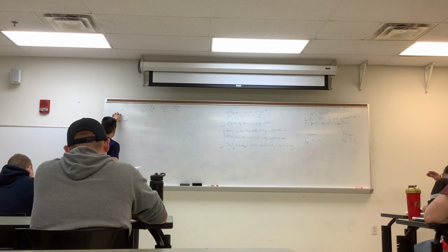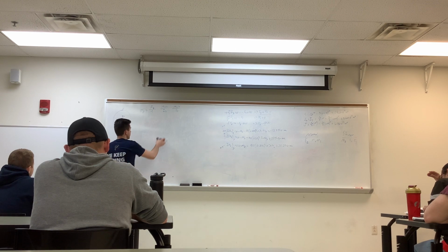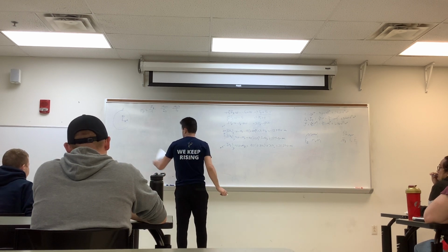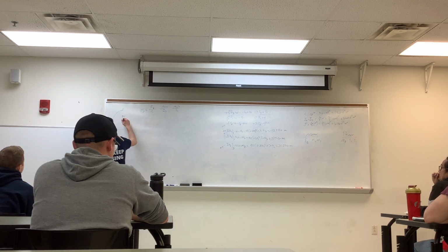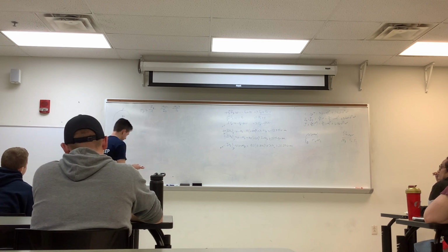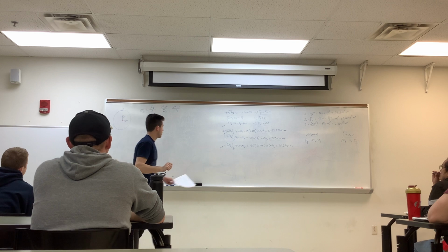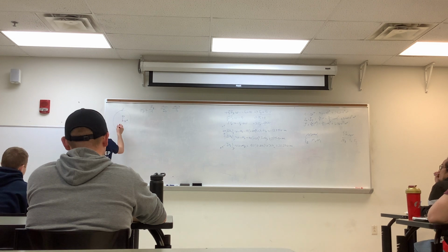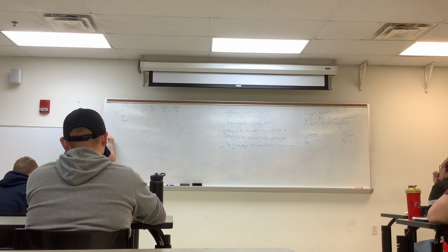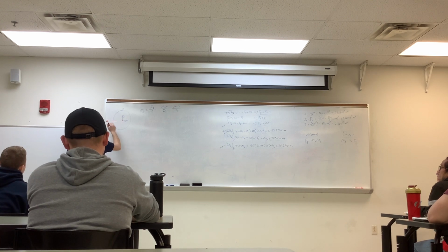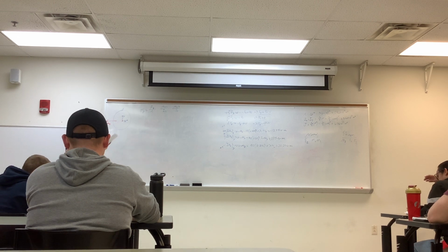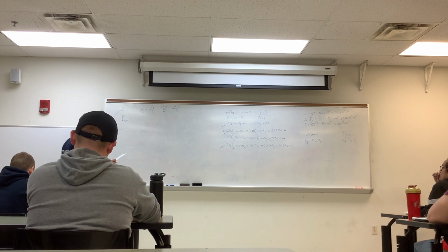So we're looking for point H here, determining whether these are both positive or negative, the moments acting on it with regard to our cross section. We have our axial force coming straight out of the center. We have our moment in the x, acting in that direction, since we assumed to the right is positive here. It happens to be a negative one, so it'll be acting in that direction. Just like the moment in the y is acting upward.